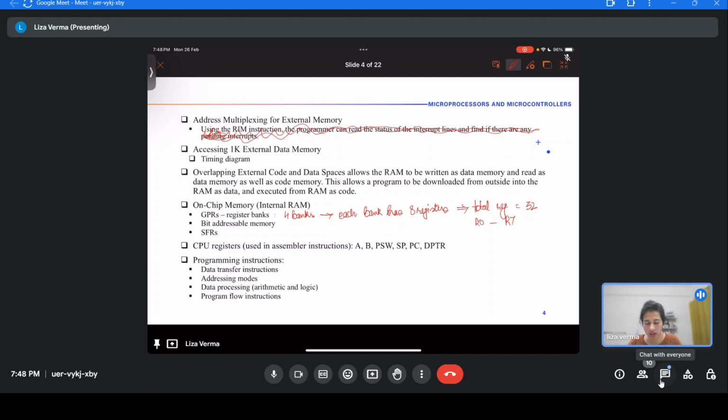If you think about how we used the registers in 8085, you might get the answer. To address or to use a register or a register's contents, what did we have to do? Let's say you want to move contents of register B to A in 8085. We'll just write MOV A, B. No, first we have to select that register bank, then only we may transfer the data. Yeah, but the main instruction would be that, right?